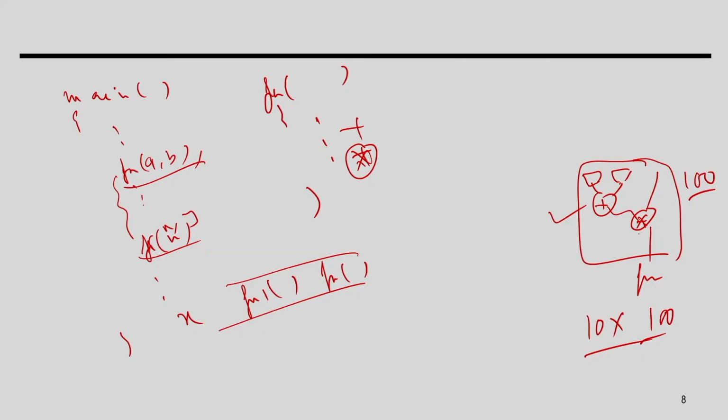There is some multiplier and adder within the function, and after the function call is done, this hardware will remain idle for the rest of the time. Even with multiple calls, after the calls are completed, the multiplier or adder for this function body will remain idle. So, my secondary objective is: is it possible to share this multiplier or adder within the function body with other operations?